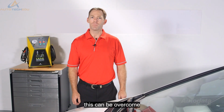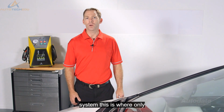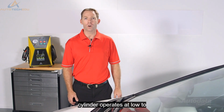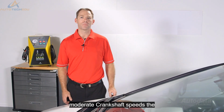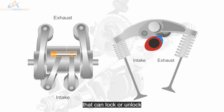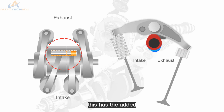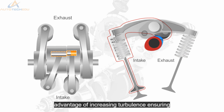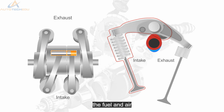This can be overcome by using a valve idling system. This is where only one intake valve per cylinder operates at low to moderate crankshaft speeds. The system uses a shuttle pin that can lock or unlock the intake rocker arms together. This has the added advantage of increasing turbulence, ensuring a more uniform mix of the fuel and air.